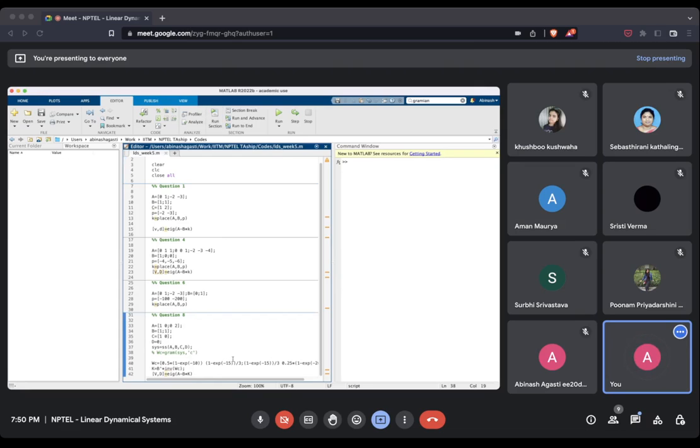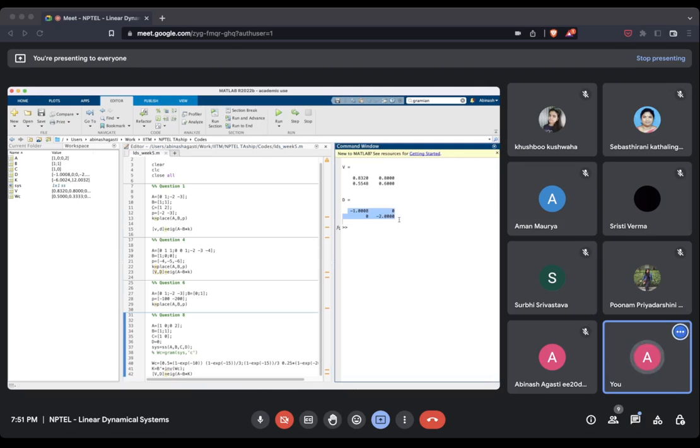Alright. Then if I just run this, I obtain that the eigenvalues of A minus BK are now at -1 and -2. Okay. So this is how you can use the controllability Gramian to obtain a stabilizing solution. But since the computation of the Gramian is usually difficult, we stick to other methods. Is that clear?